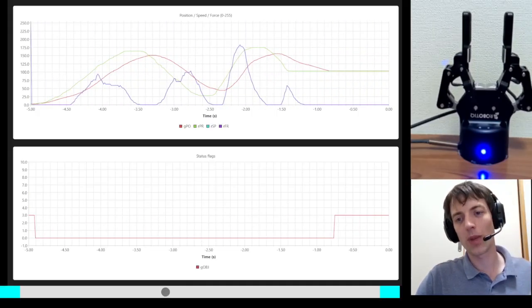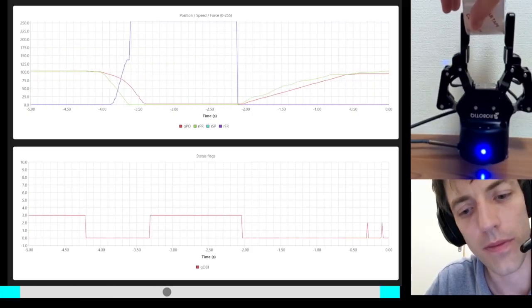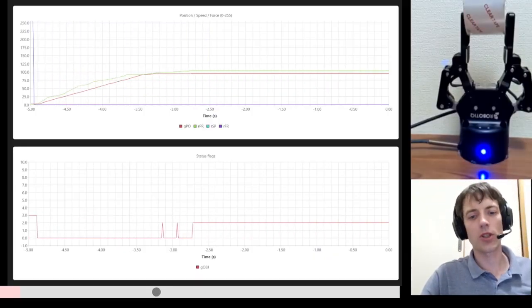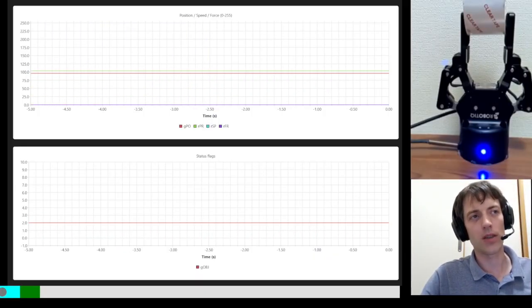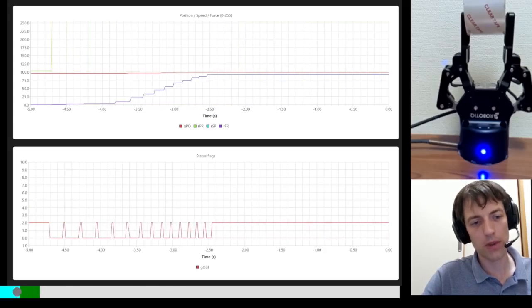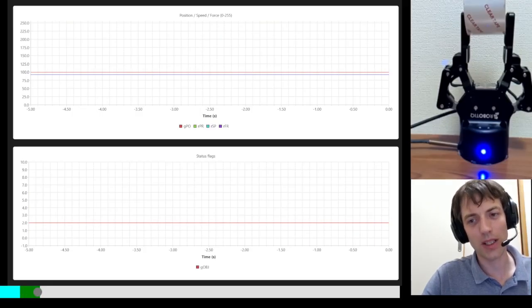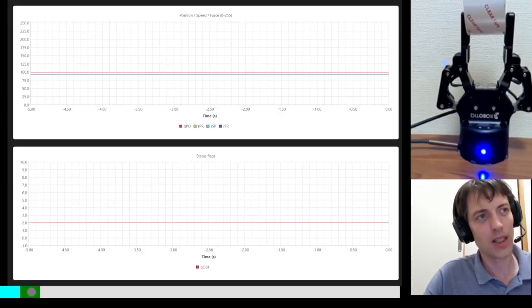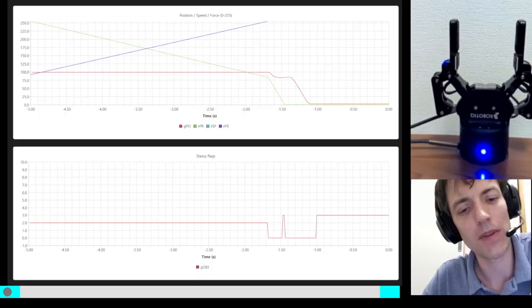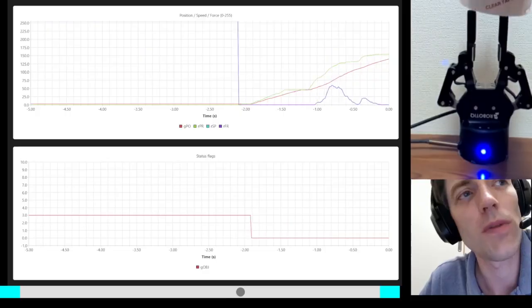So I'm going to make it a bit faster again. So I'm closing on the object. Okay, I get the information that I am on the object. I release the joystick. I enter in the force mode. I set a specific force. Then I go in deactivate mode. I go back in activate mode, but I don't push, I don't set any further force. Then I go back to the deactivate mode and I get a release. And it works also if you pick the object from the inside.